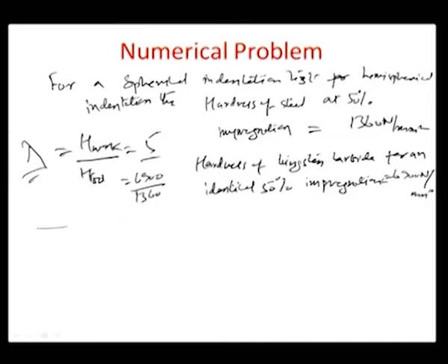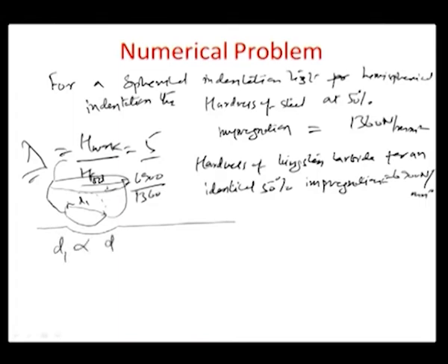So, as you know, here we had already assumed that, let us say for example, this was the deformation that the grain surface had. So, the grains are represented by some projections of different diameters, right, and this diameter here, for example, of this particular sphere is d1, okay, and the average grain diameter somewhere here is maybe about small d. So, in this case, as I told in the previous Shaw theory, d1 is found to be proportional to square of d, equal to mu times square of d.